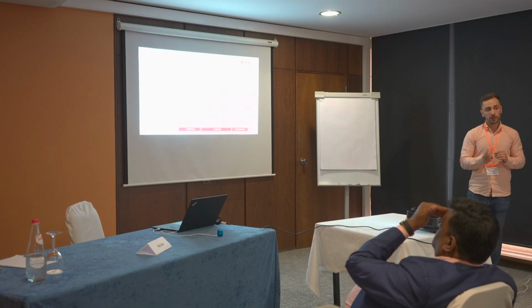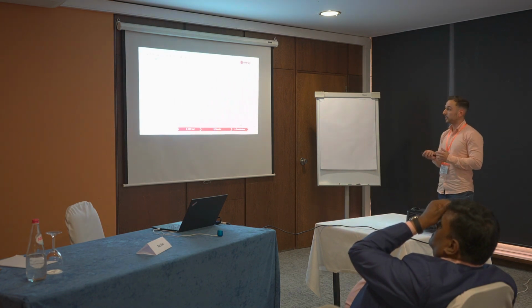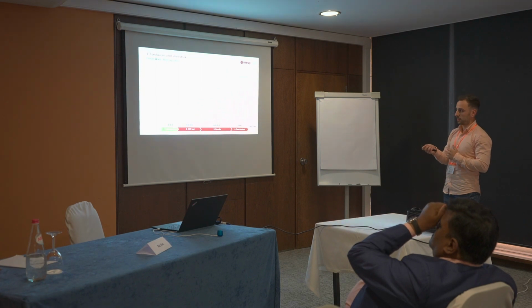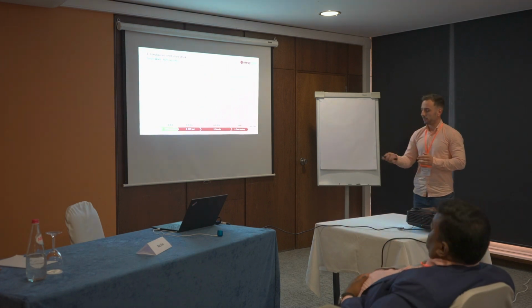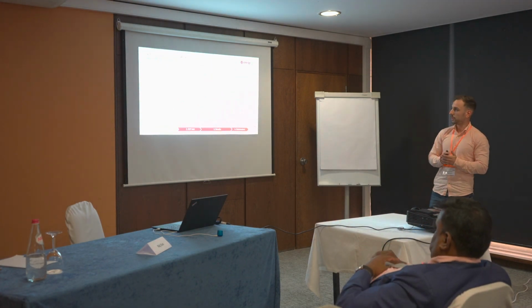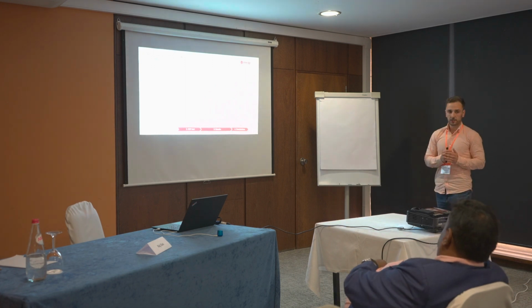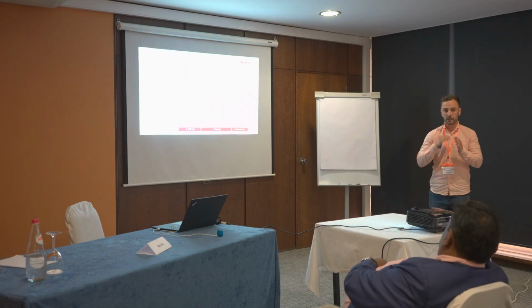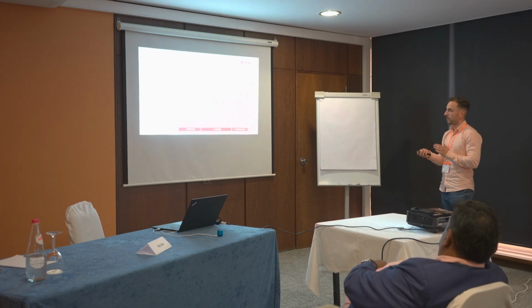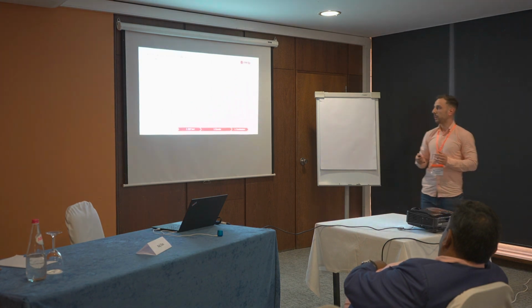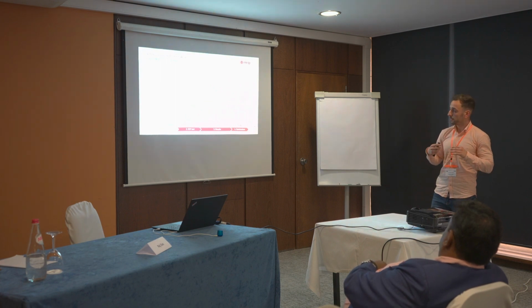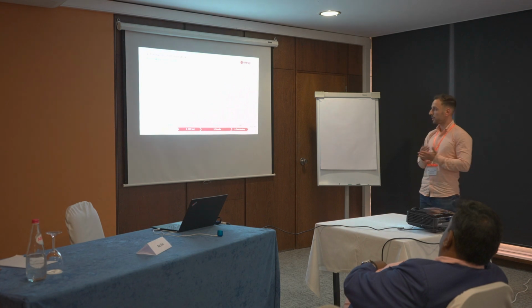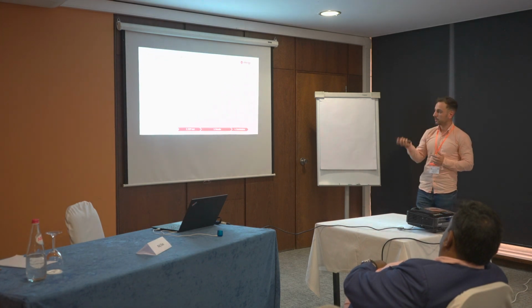We are going to perform new dynamic tests by including the passenger side door. I think it's important to monitor the driver area, the residual space. We are studying internally replacing the composite outer panel with DCPD polymer, a polymer highly used in the automotive industry. According to the results, we are going to investigate possible structural changes in order to optimize the structures.